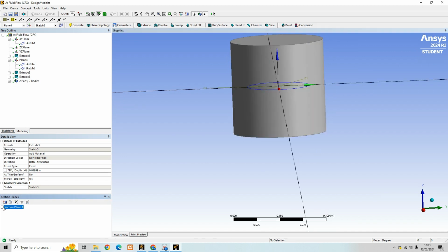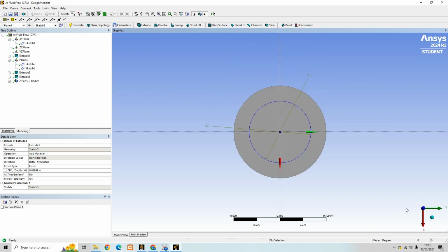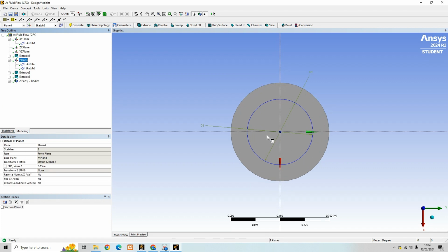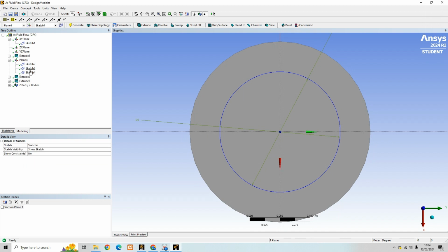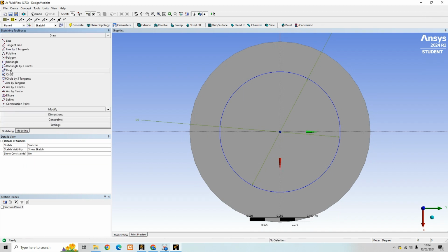So one more thing we need to do now is actually create our impeller. So I'm going to do one final sketch. This time it's not going to be a circle. Just going to zoom in here slightly. Going to create a sketch on the same plane, the plane 4. This time we're going to model some really simple impeller blades, just using some rectangles, and we're going to nearly entirely fill the rotating region just to make sure that we actually get some movement of fluid flow.